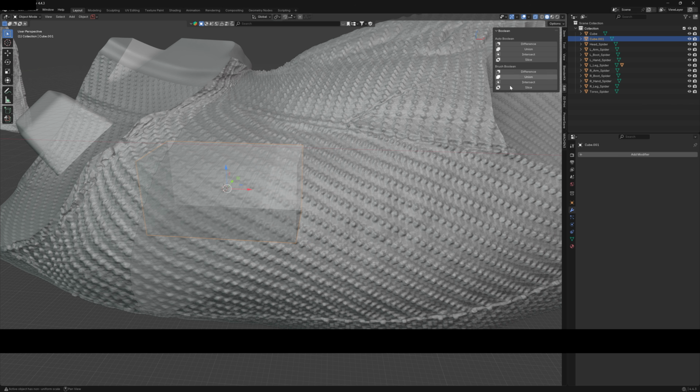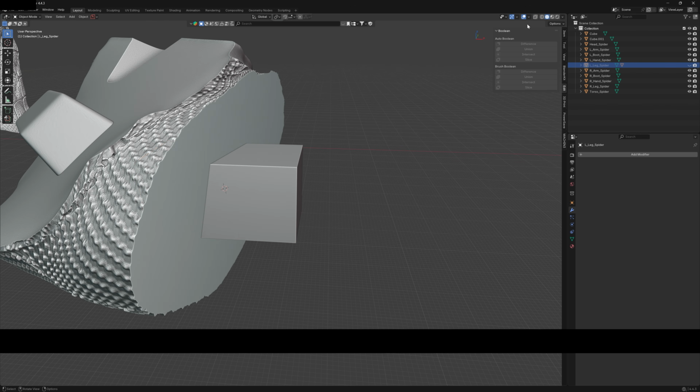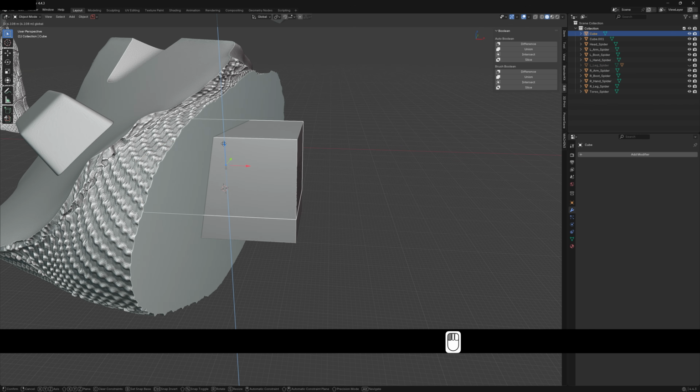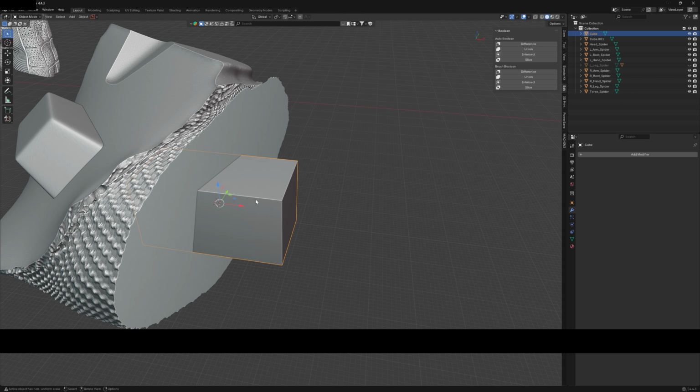So now we have, if I just hide this chat, switch off X-ray mode and move, you now got 2 exactly the same shapes. But obviously the hole for the peg needs to be bigger than the peg itself, so we just need to scale it. So we go up to scale, to item, scale. If you see all these weird numbers, it's because we've stretched it.